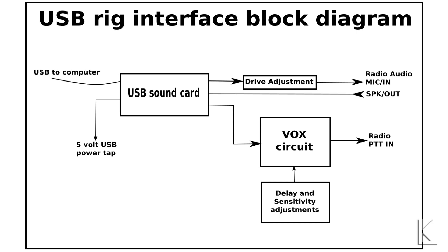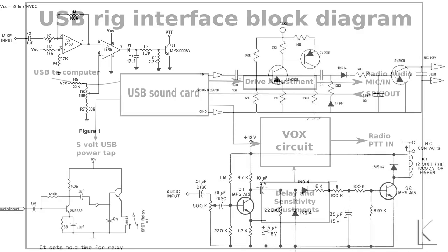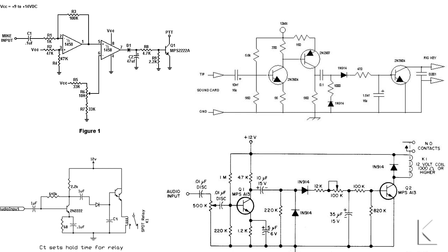The delay would also be useful for modes like slow scan TV or fax, where some pockets of silence will occur during the transmission. The VOX circuit can be tricky. You need to detect a low audio level and somehow short the push-to-talk line on the radio to ground. There are many circuits out there to choose from, many requiring external power of 9 or 12 volts. If you want to change their behavior, you need to fiddle around with the electronics, and it can take time.